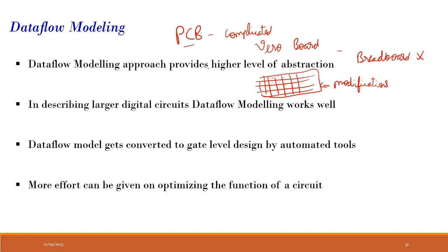So my advice to you guys is to make a simple buck converter. Don't go for very fancy components. Just make sure the ratings are fine, how much current it can carry, the voltage, with some safety factor; take all those things into account.